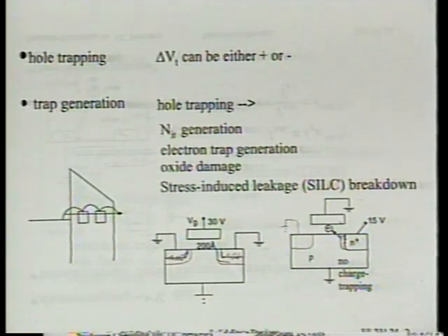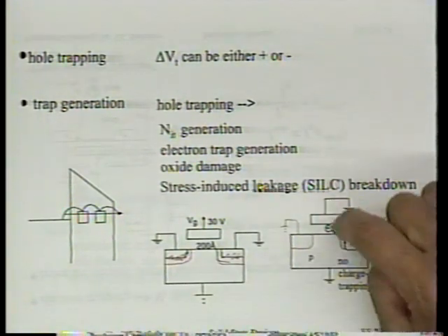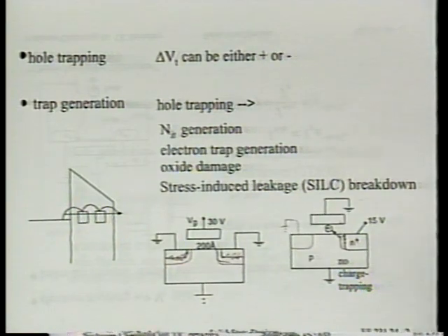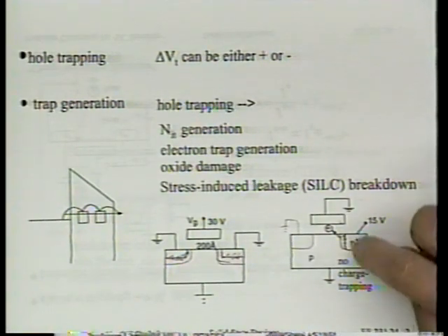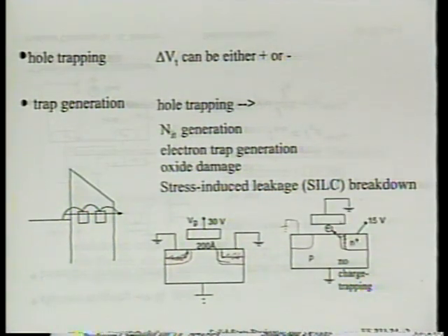In principle, GIDL itself, that is gate-induced drain leakage, has to do with band-to-band tunneling, and can happen before the junction breaks down. And if that happens, the oxide is not damaged very much because we don't have a lot of hole injection. But with just a little bit more voltage, the hot hole injection becomes quite strong. You can even measure the hole current coming out, by the way. That's another way to confirm that under this condition, holes are injected into the oxide.